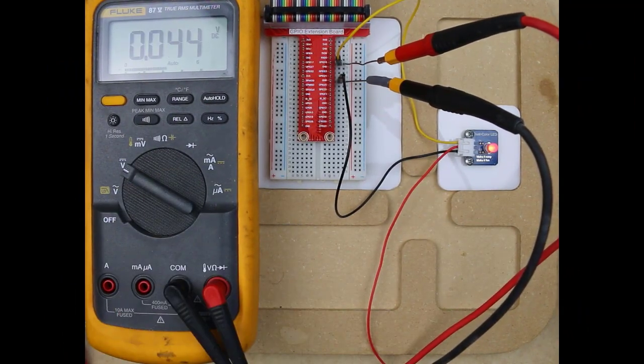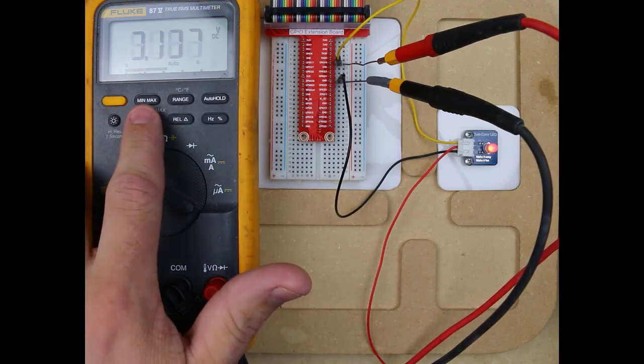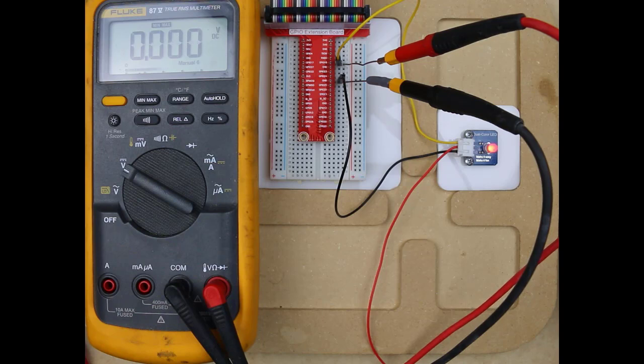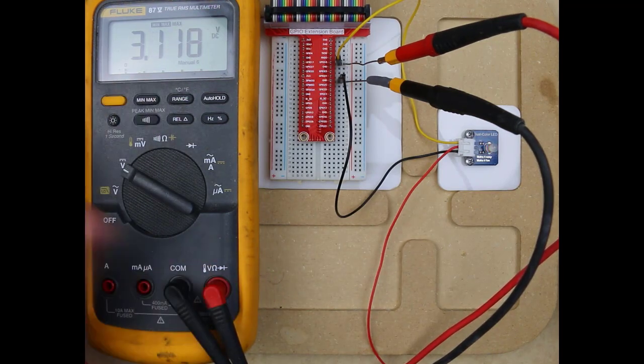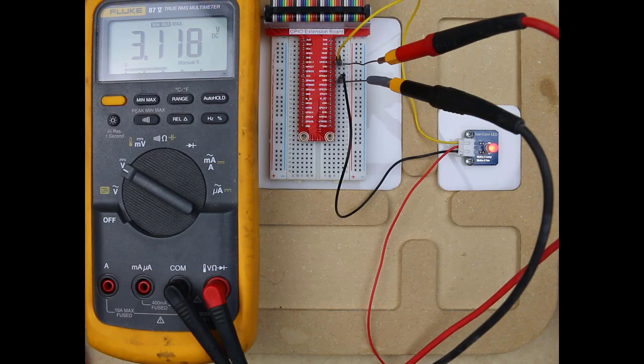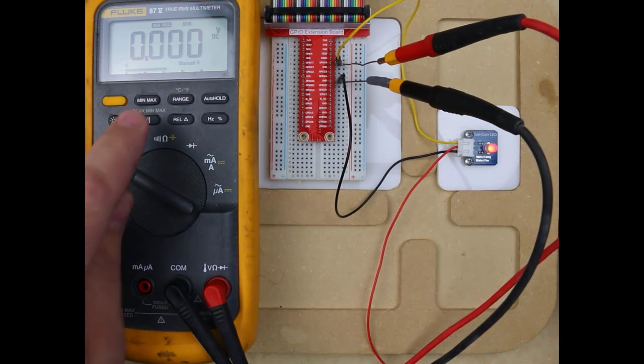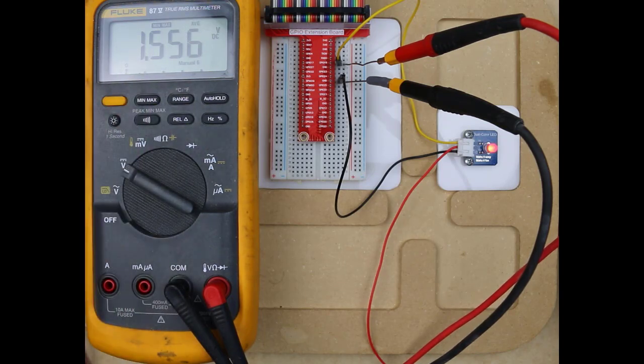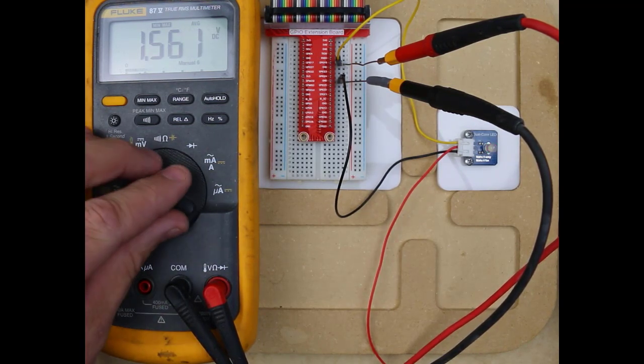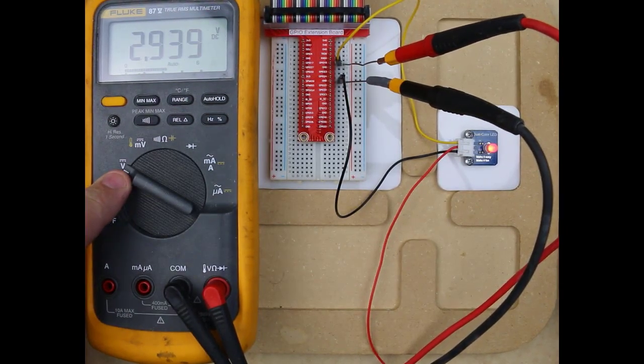Rotate the dial of the multimeter to volts DC. We can see that the range of the volts is changing from somewhere around 0 to 3.1. In order to get a more accurate measurement of the voltage that we are seeing, we are going to use the min-max button. If you press the min-max button, you'll see some beeping that will occur when it gets a new value for min and a new value for max. If I press the button again, I will now get the maximum voltage that the meter will read. If I press it one more time, that will give me the minimum voltage. Here we see it. And then I press it one more time and I get the average voltage. So we can see here that we're getting about 1.56 volts on average.